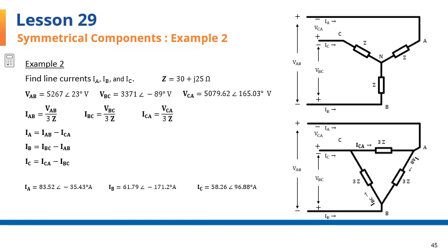However, the symmetrical components method proves its value when applied to very complex power systems in unbalanced operation, as it separates the system into 3 separate but related sequence networks and applies sequence voltages or currents to each and collects the results to determine vital parameters such as short circuit currents, over voltages, etc., which are all useful information in fault analysis and design of protective systems.